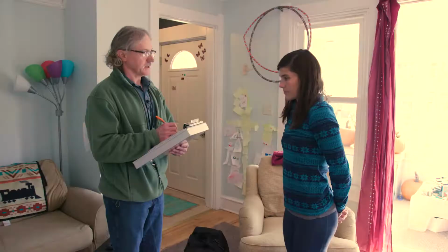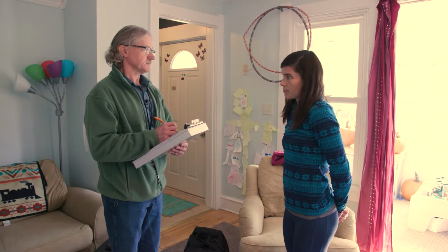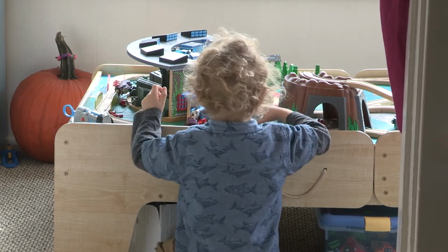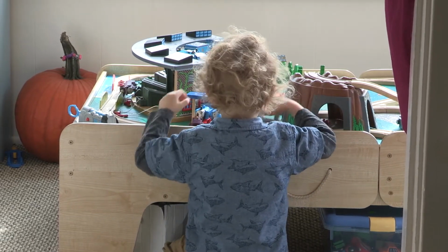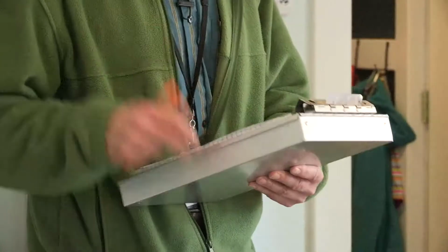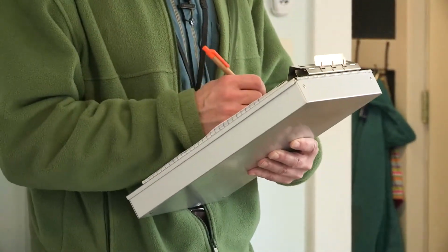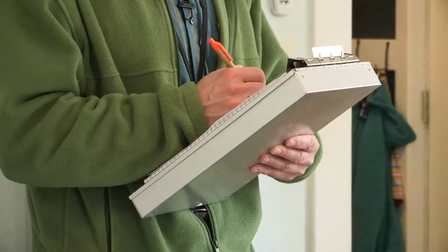The goal is to get as much information as possible about where children eat, sleep, and play, and any possible non-paint sources of lead that could exist. For EBL cases, this could reveal other locations outside of the home that will also require assessing. After the interview, the next step is to complete a building condition survey and visual assessment of the property.